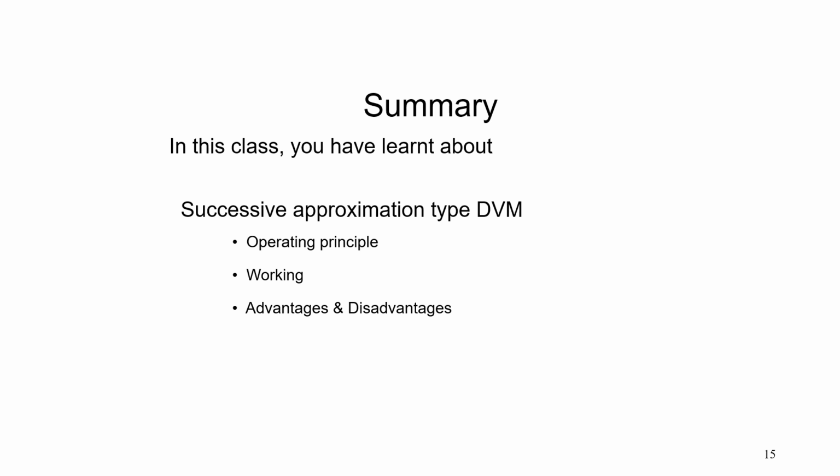So to specify a digital voltmeter, we have to specify different parameters like the display time, how many digits display it has, what is the input range of the voltage which we can measure, what is the accuracy, the resolution of the meter, input resistance, the input capacitance, what are the output signals, do we have the zero adjustment, do we have the overrange indication, what all it can measure, the functions.